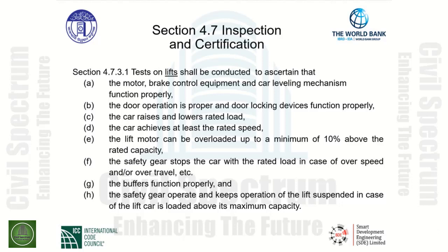F, the safety gear stops the car when the rated load in case of overspeed and or over travel, etc. G, the buffers function properly. And finally, H, the safety gear operate and keeps operation of the lift suspended in case of the lift car is loaded above its maximum capacity. These are the tests on the lifts that need to be conducted for safety functions of lifts.